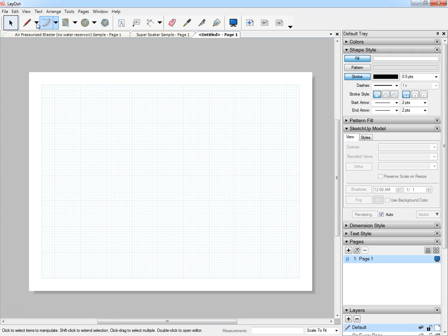The basic tools or drawing tools are up here at the top of the screen. You have the pencil tool, you have an arc tool: 3-point arc, 2-point arc, and a regular arc. Those are for making the elbow connections. There's a rectangle, rounded, and then these other two, circles, and then the polygon tool where you can decide on how many sides you'd like to use and create a polygon.